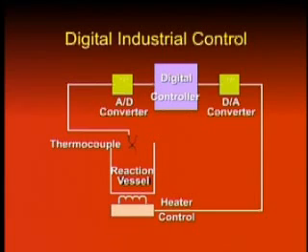The voltage representing the temperature is converted into a digital representation, which is fed to a digital controller circuit. The circuit generates a digital value corresponding to the desired amount of heat. The digitized output representing the heat is converted back to a voltage value which is continuous and is used to control a valve that regulates the heat.